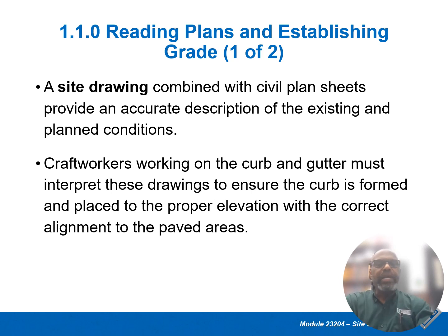So, reading plans and establishing a grade. In other words, by taking the plans, we know we're putting the curbs in the right height and in the right position. A site drawing combined with civil plan sheets provides an accurate description of the existing and planned conditions. So again, the plans would show what it is and what it should be.